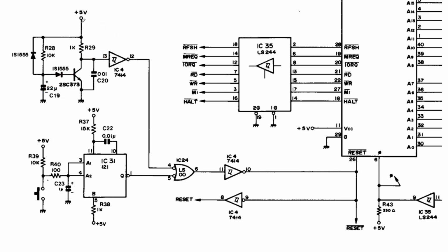But after a while, through this resistor R28, the capacitor will charge. And once it's charged, then through this diode, there will be a positive potential on the base of this transistor. And the transistor will then close, meaning that the potential of the emitter, which is ground, will be here on the input of the inverter.